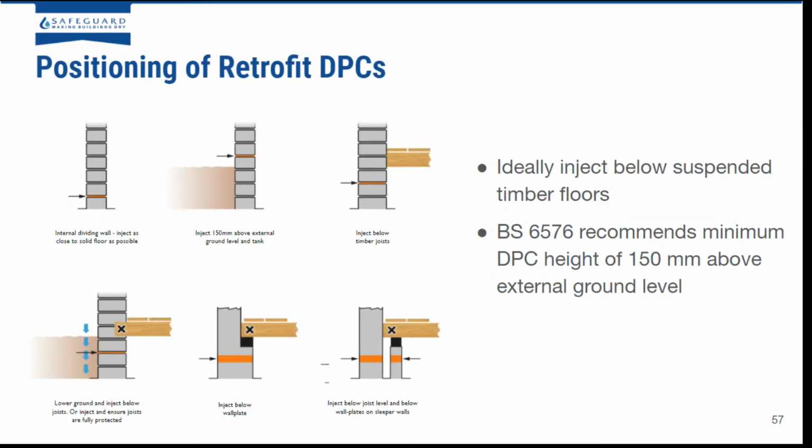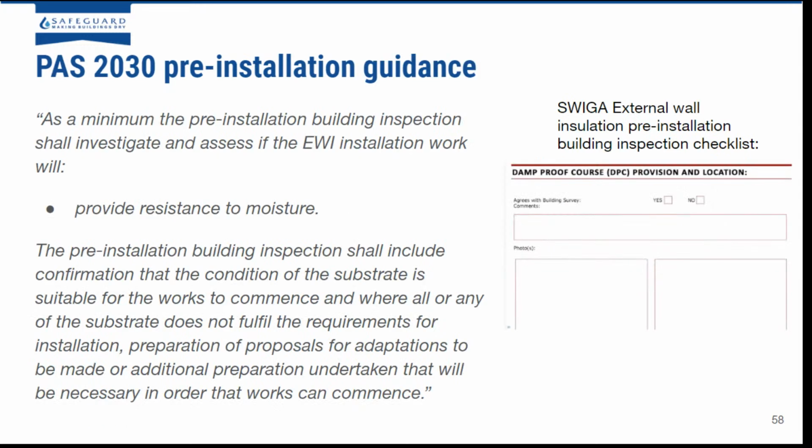So we have a lot more information on retrofit DPC installation, lots of it available online. We have a booklet which is freely available, so if you want to read up on that, I recommend it. One thing to say is that the Solid Wall Insulation Guarantee Agency does require proof that a DPC has been installed in order to get your guarantee. So they require photos of that to make sure that you have the minimum requirements for EWI.